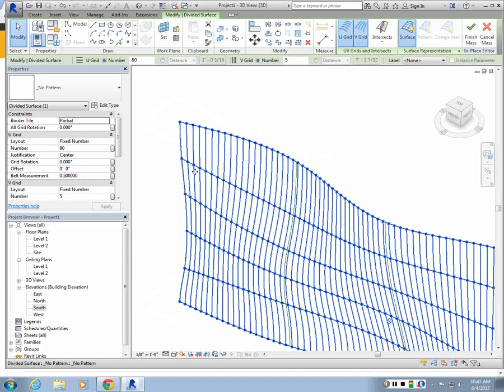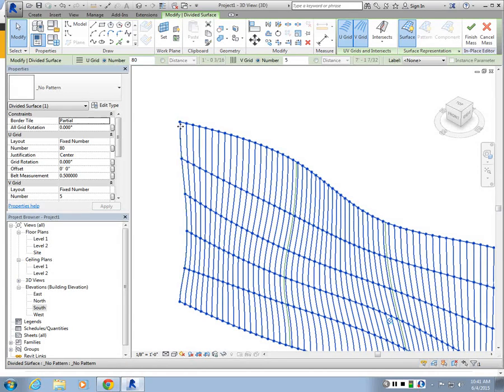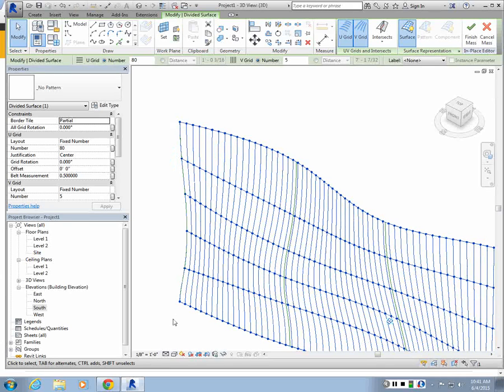So my adaptive component would be snapping to these points. So I'm going to say this adaptive point is this point on the surface. This adaptive point is this point. And then Revit is going to use that information to generate a flexible panel here for me using the adaptive component constraints, thickness values and other types of extrusion values, the profile.